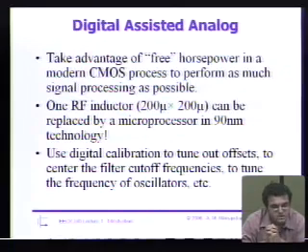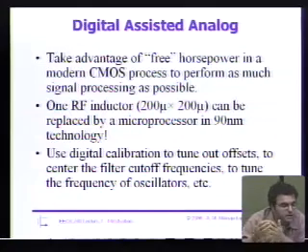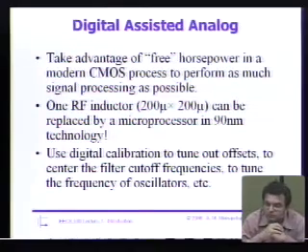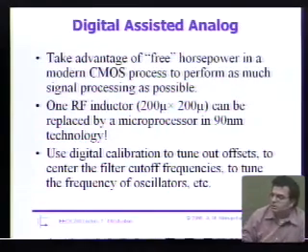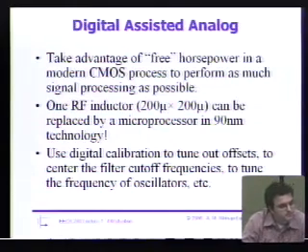Well, it's harder and harder to do that with modern advanced CMOS processes. So instead of spending all his time optimizing the gain stages, Boris said, I'm going to use lousy analog. I'm going to let the analog circuits make mistakes, and use digital circuits to correct for those mistakes. I'm going to detect the gain errors and linearity errors and correct for them digitally. That's a fundamental shift in the way you would design a circuit, and I think we're going to see a lot more of that going forward. Okay? Questions or comments?